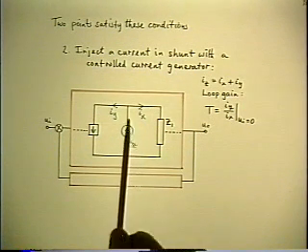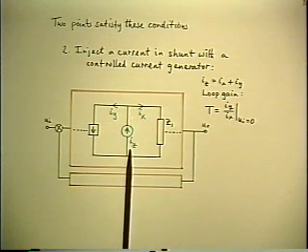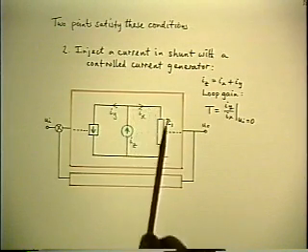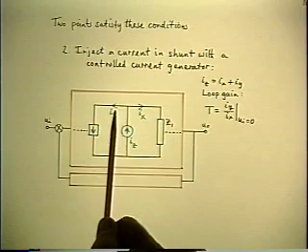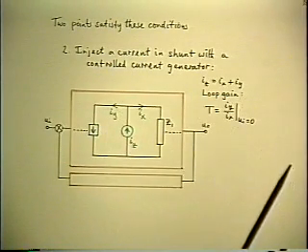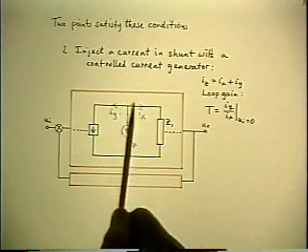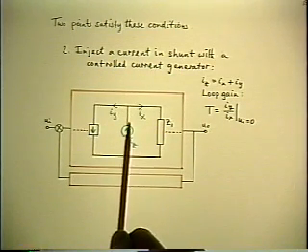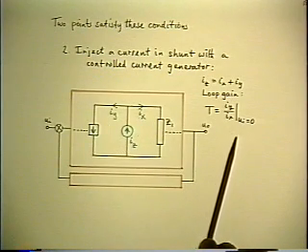Then you can do injection by the dual method. You can inject a shunt current, IZ, and it splits into two currents, IX that goes forward, it comes back up again as IY, and the loop gain is IY over IX. And there is a phasor triangle of currents, just the same as there is for voltages, and the loop gain is the ratio of two currents.